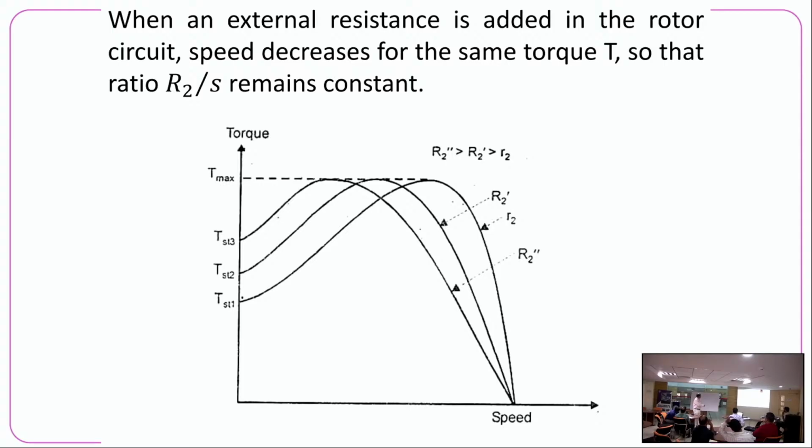You are telling this point should be here. No, I am not. This starting torque should be 0? That is what I am telling. Your point is why the starting torque is not 0. First thing, if the starting torque is 0, motor will not start. Actually, single phase induction motors' starting torque is 0. Your domestic fans in your house are single phase induction motors. Their starting torque is 0. But if the starting torque is 0, motor will not rotate.